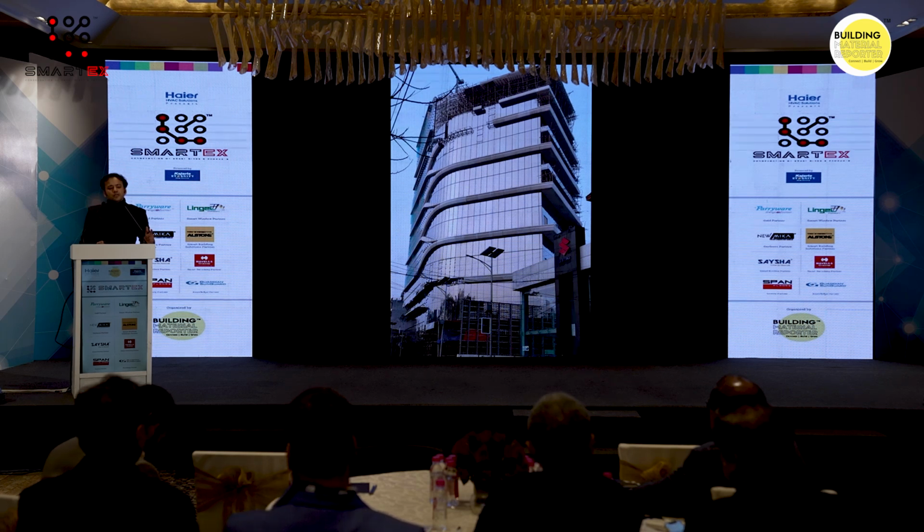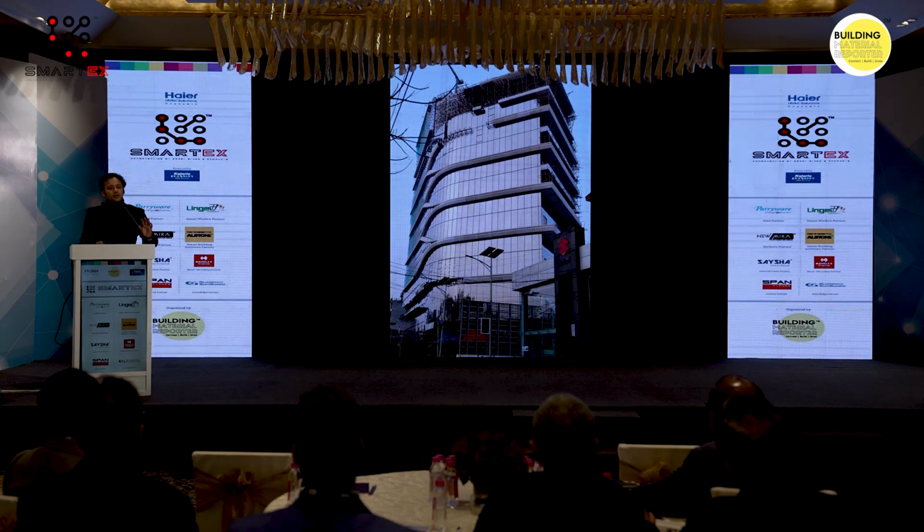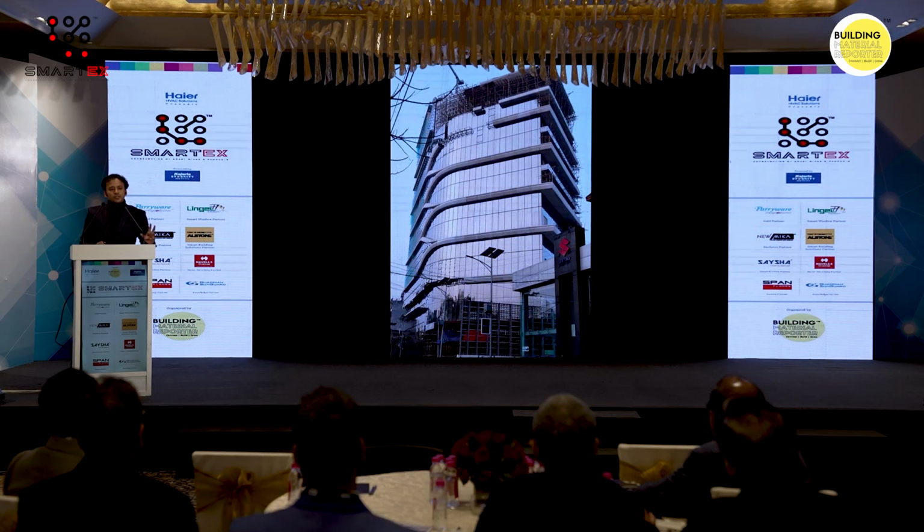To hang something as complex and as heavy as a GRC, you would usually remove the spandrel panel, go directly into the beam and hang it. But in this case, we did not expose the beam. It's a full height glass. We worked out a special detail for the mullion, and there's only brackets coming out of the mullions on which it's all a unitized system. So nothing is being manufactured on the site. It's all factory produced. You just bring, hang, and you go home. The idea was to really look at producing things in factory, because in factory everything is much more controlled. If I was making GRC panels on site, maybe the factory manager is not there. The quality of staff will be lower.